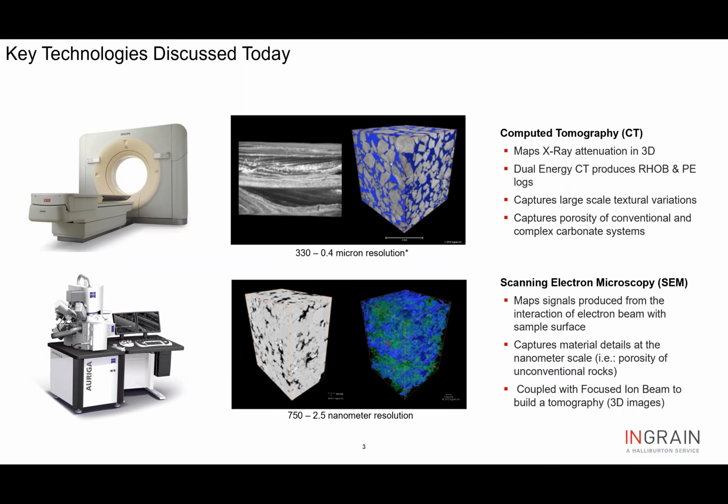And at that point, either from the CT scan or from the SEM, both of these you can bring into your computer and characterize the rock, or you can play with that, or do all those different simulations that I have already mentioned. Like the SEM, CT also has a very high resolution method that is called the microCT. So instead of the whole core rock, you can actually cut a very thin pillar of a rock, which may be 2 or 3 millimeters in diameter, or maybe even go smaller than that, and analyze that using the microCT measurement.